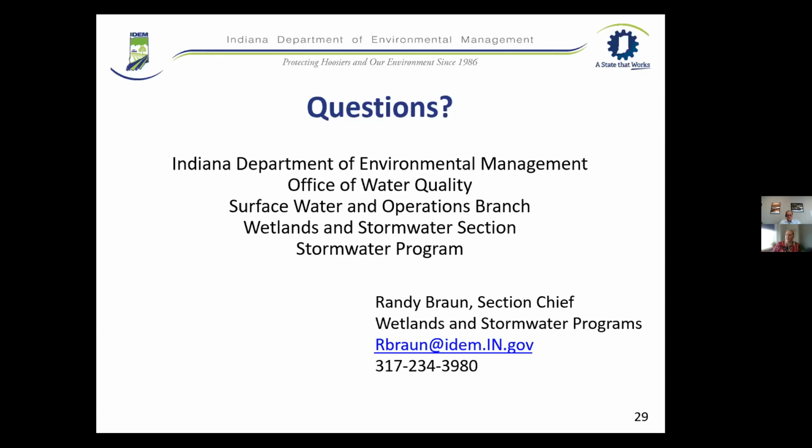So we basically say list all your outfalls to characterize them. And then we also have an option where if you have similar industrial activities going to two different outfalls, you can call an outfall substantially similar, and then you can choose to monitor one over the other. We typically will look at those when an NOI comes in.